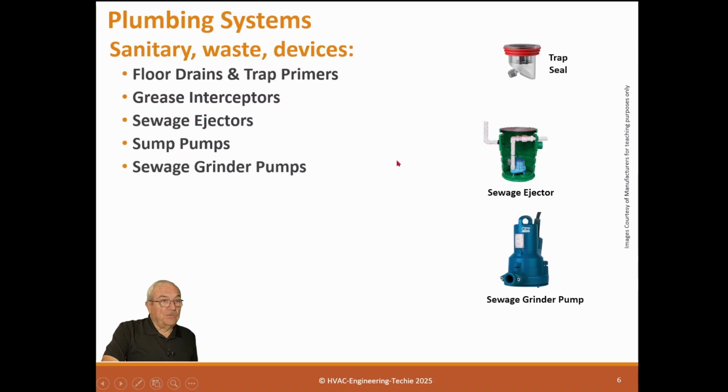Then we have sewage grinder pumps. Instead of putting a regular pump in there, you can put in a grinder pump, which actually grinds up the sewage in case you have a facility where people flush a lot of material down the toilets. These grinder pumps are designed to chew that up so it doesn't clog the sewer lines.